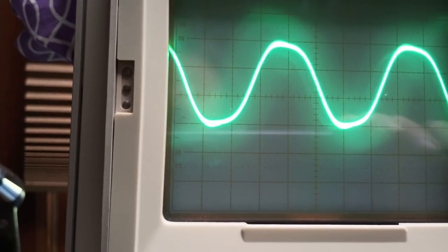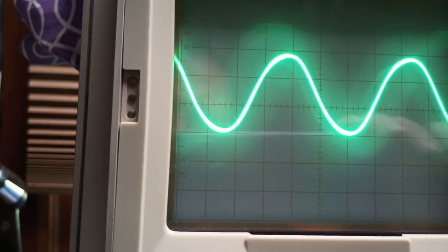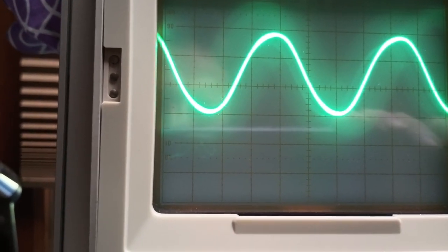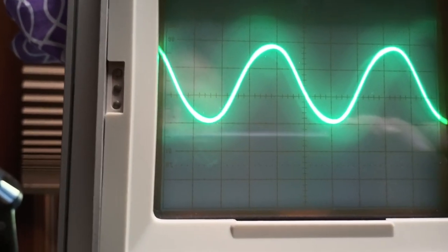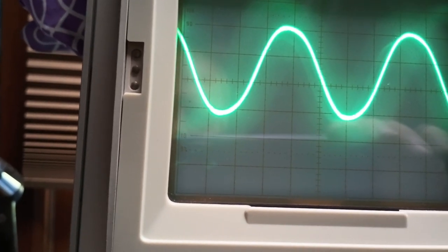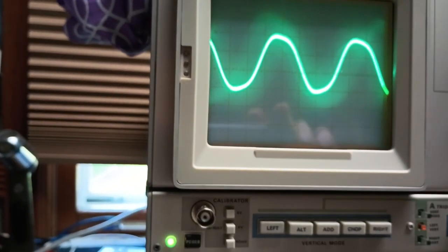But from about 21.0 to 21.5, which is where we can't transmit, I'm just using test equipment at low power, that indicates more or less a resistive match, and that shows a pretty broadband antenna. So something to mess with.